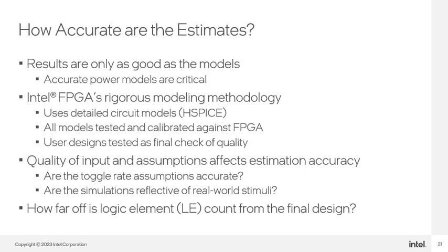To that end, Intel uses a rigorous modeling methodology where detailed circuit models are created using HSpice. All models are then tested and calibrated against the actual device silicon. To further guarantee the accuracy of the models, power estimates are performed on the models using a variety of actual user designs.